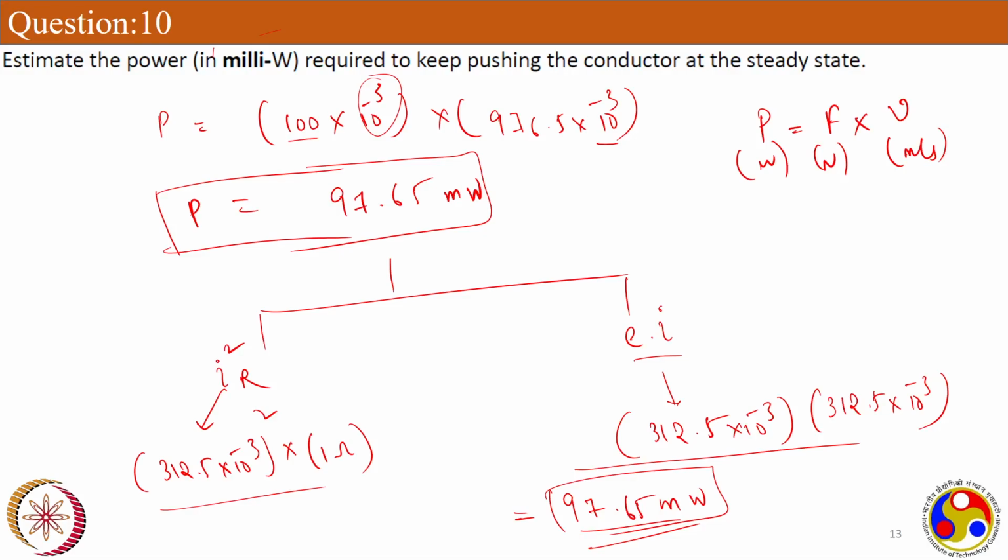Yeah, that's what we discussed today, right? Even if it's a magnetically coupled circuit, even if there is no physical connection, based on the dot polarities you can decide the polarity of the voltage. Whether the current is entering the dot or leaving the dot, only that will matter. So don't bother about the bottom connection?